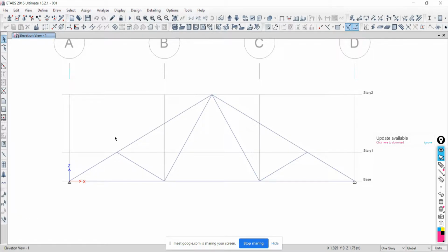But what is the use when you are dragging from left to right? For this case, only the things which are completely coming inside of this box will be in selection. See, when I'm dragging like this, what things are completely coming inside of this box? Joint, sir. Only the joint, so that's why one joint is in selection.